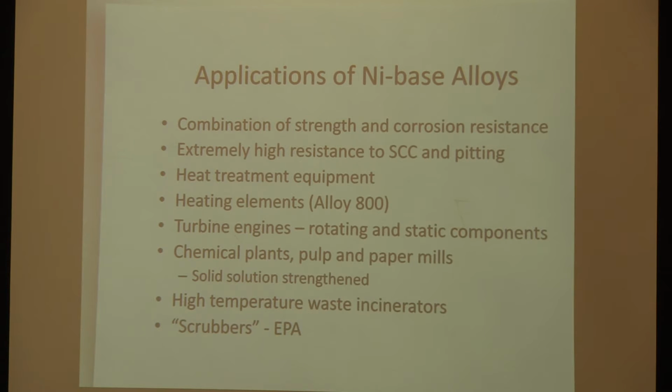Some places where these alloys typically get used are heat treatment equipment, heating elements, and turbine engines, where both rotating and static components are often made of the Inconel alloys. Chemical plants and pulp and paper mills often use the solid solution strengthened alloys. There are also high temperature waste incinerators and scrubbers, used for EPA requirements for cleaning the air from power plants and other things.